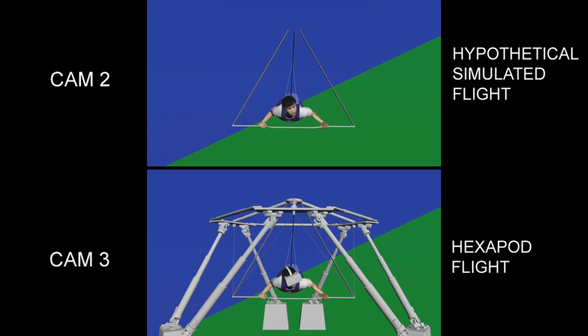I mentioned earlier that a pilot who steers to the left or to the right will have to overcome some resistance, especially when steering out of a turn. This initial resistance can very easily be simulated by the motion simulator. The simulation software gets steering input from the pilot. The software also controls the pistons. So when the software gets steering input, it can hold the pistons stiff for a short moment, giving the pilot the feeling of resistance, and then start to bank.